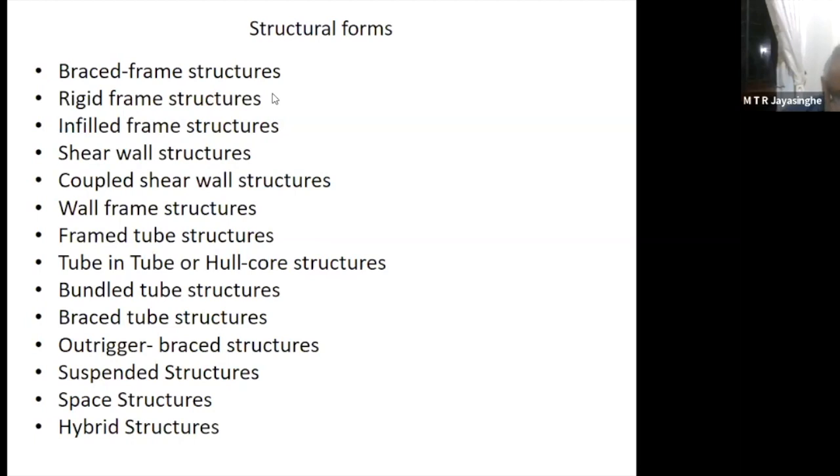It's not a moment distribution, because if you have two adjacent slabs having different spans, then you are not going to get the same support moment. But you can't have two different support moments because that is going to rotate the beam. So what you do is adjust the support moment sufficiently so that the rotation of the beam can be made almost zero. So that is the answer.